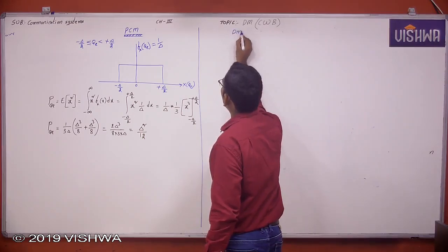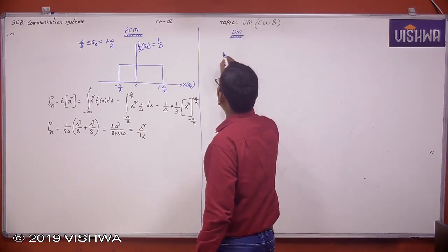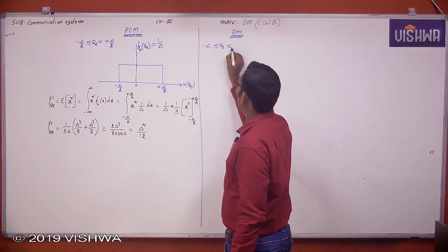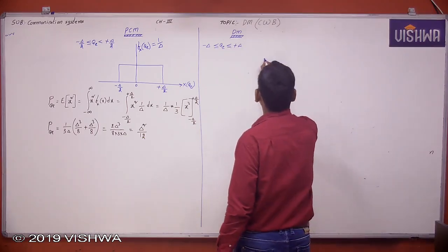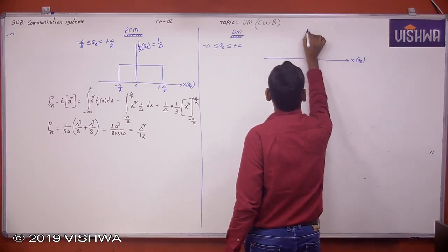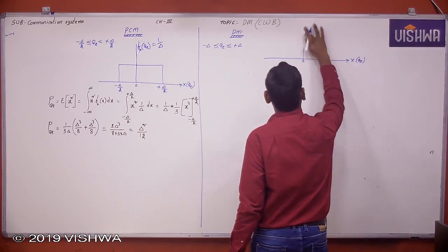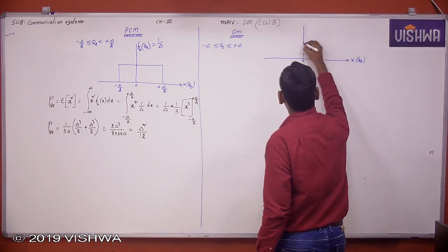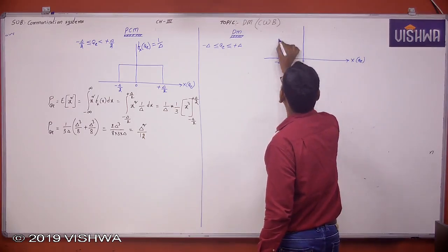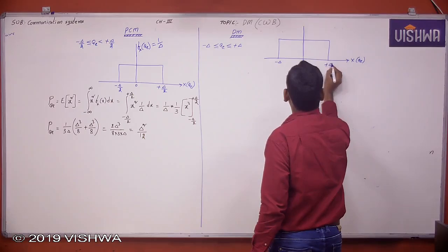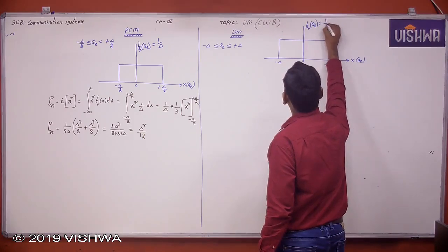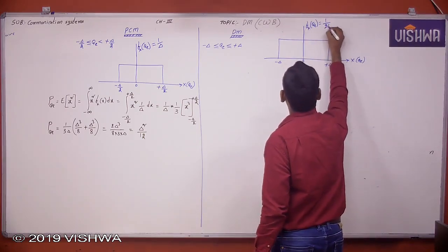This is a delta modulation. In delta modulation, the quantization levels are only two, whether it is minus delta or plus delta. So this is also a uniform distribution. This is the quantization noise power. The quantization errors are uniformly distributed in the interval of minus delta to plus delta. Now what is the probability density function? Uniform distribution function, which is nothing but 1 by b minus a, 1 by 2 delta, right?